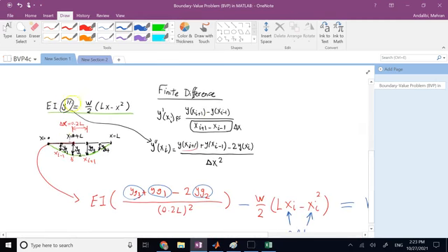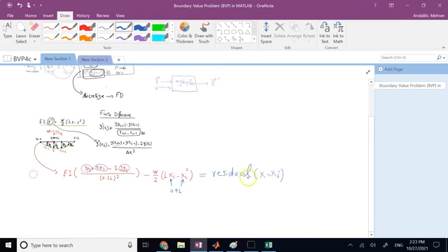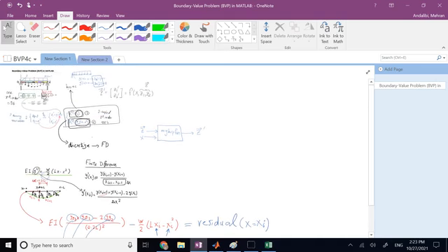They convert your continuous equations into discrete equations like this using the finite difference method. They calculate residuals, they start from some initial guess, and then their recursive algorithm tells you how to update these so that these residual terms become as small as possible. Good. So you see why you need an initialization.